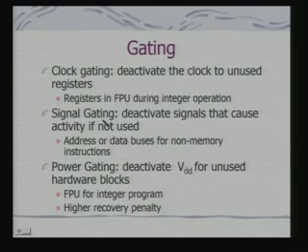Next thing is signal gating. Deactivate signals that cause activity, if not used. So, address or data buses for non-memory instructions. When they are not being used, I can deactivate them and effectively save energy there.